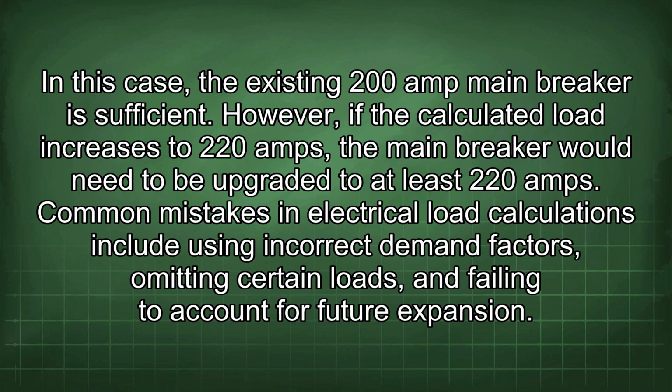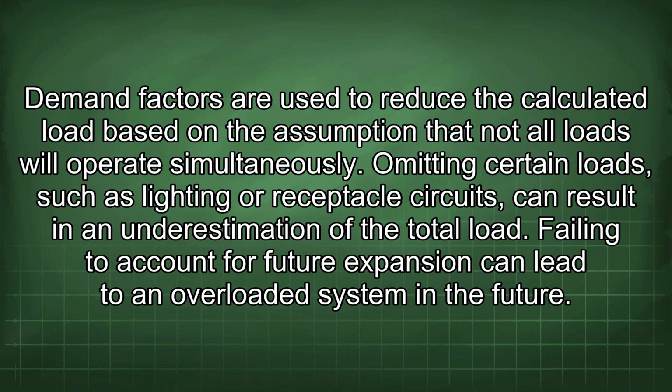Common mistakes in electrical load calculations include using incorrect demand factors, missing certain loads, and failing to account for future expansion. Demand factors are used to reduce the calculated load based on the assumption that not all loads will operate simultaneously.